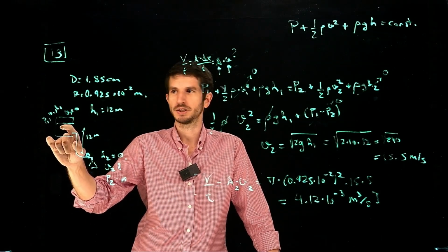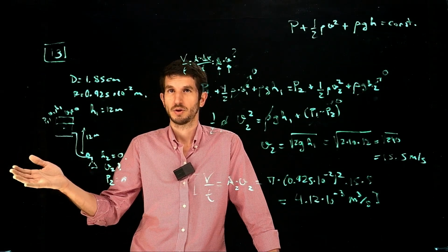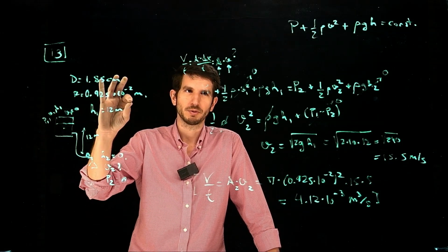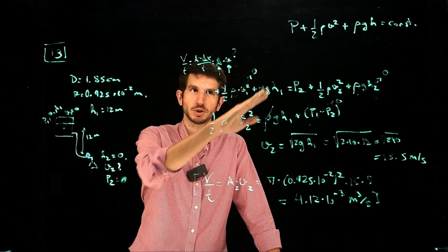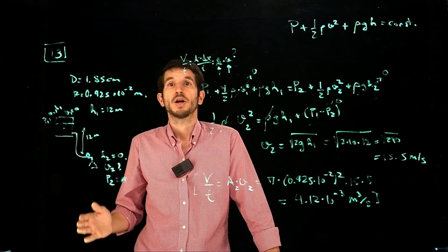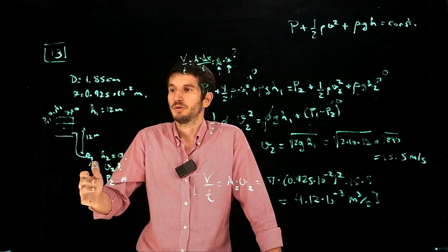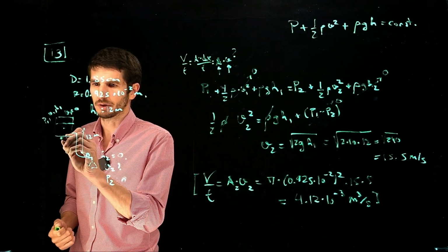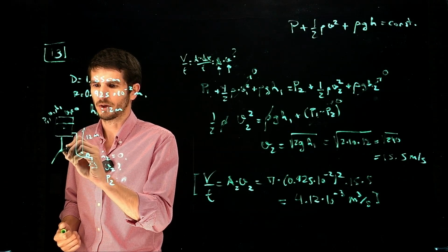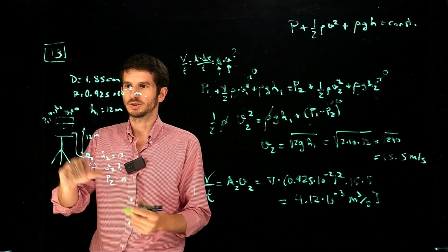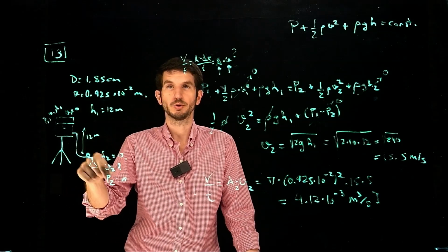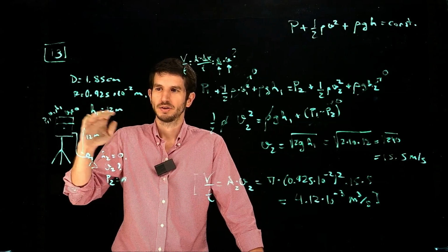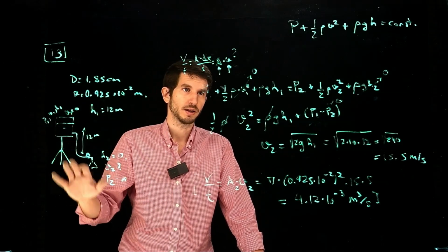Why do we say the velocity here is 0? If you observe, the tank is not moving. So yeah, you could say, as the liquid goes, this needs to flow. But it's going to be flowing so ridiculously slow that in the first approximation, you can take that to be 0. If the tank was very small, then yeah, you would have to consider that. But that's not the kind of example that we're talking about. If we're talking about a water tower, right? That water tower is going to have a huge volume for the amount of volume that you're getting out. So at every single instant, the velocity here is going to be negligible in comparison to the other one, so you can disregard it.